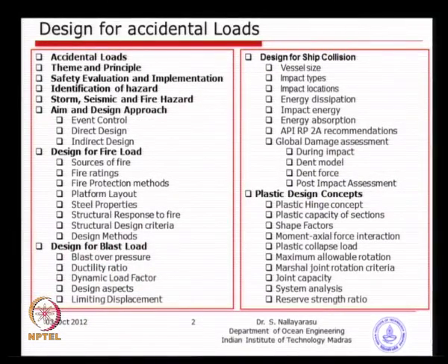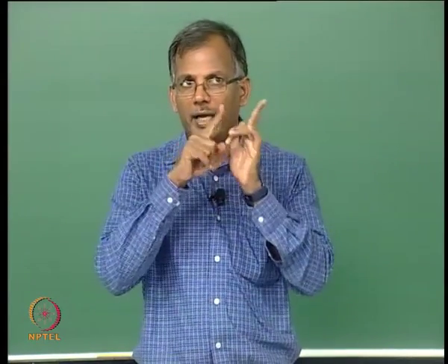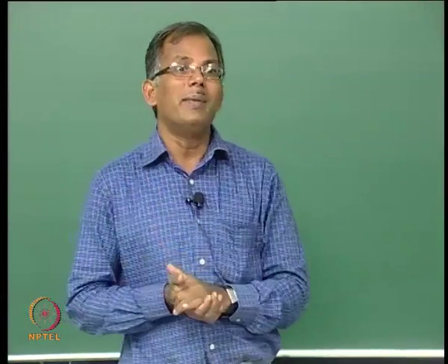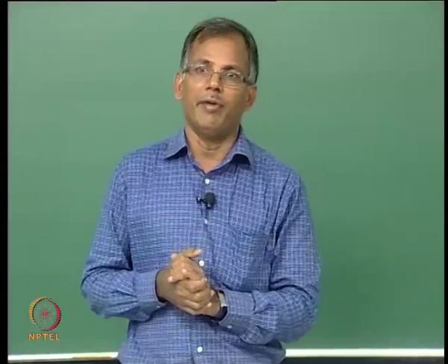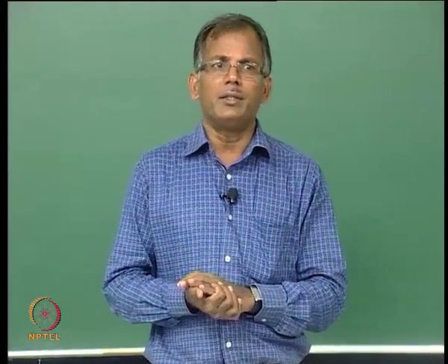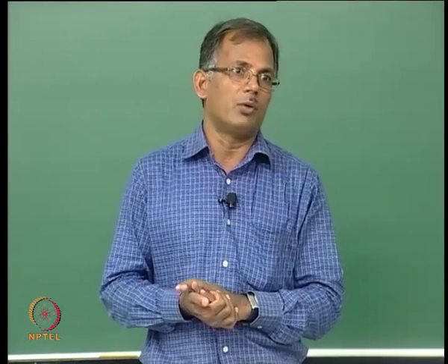We are going to use that concept rather than simply going for a simple elastic beam theory, bending moment calculated, elastic section modulus, allowable stress, applied stress. Those things we will not use because that may prove to be too expensive. So, that is why our idea has shifted from allowable stress to stress based on the ultimate strength of the structure until failure. So, this whole subject is very important in terms of the ultimate strength principles that are going to be used.